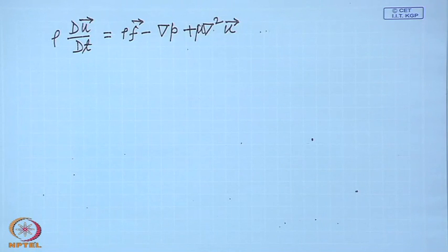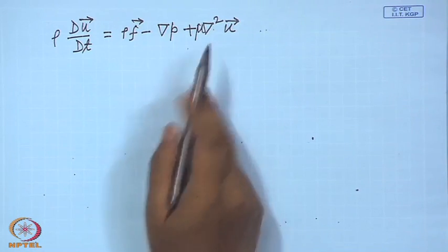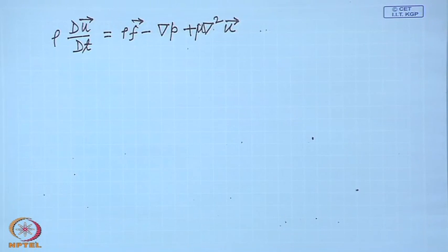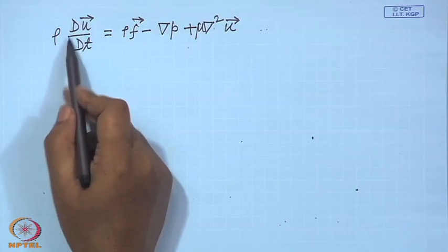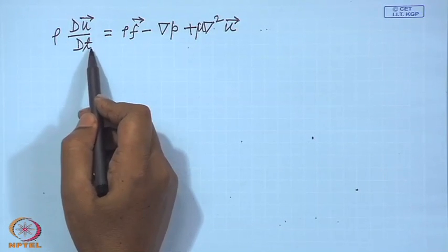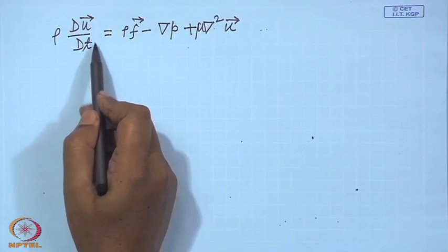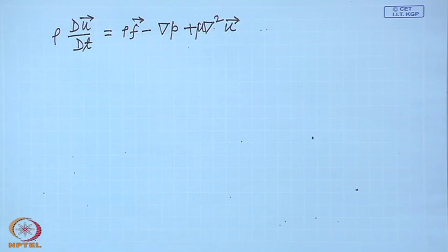These 4 partial differential equations, of course, the continuity equation or equation of mass conservation is a first order partial differential equation, while this is a second order partial differential equation. The equations are nonlinear, because in both cases, whether the continuity equation or this Navier-Stokes equation, this term is present, which as you know can be written as du_i/dt plus u_j du_i/dx_j.